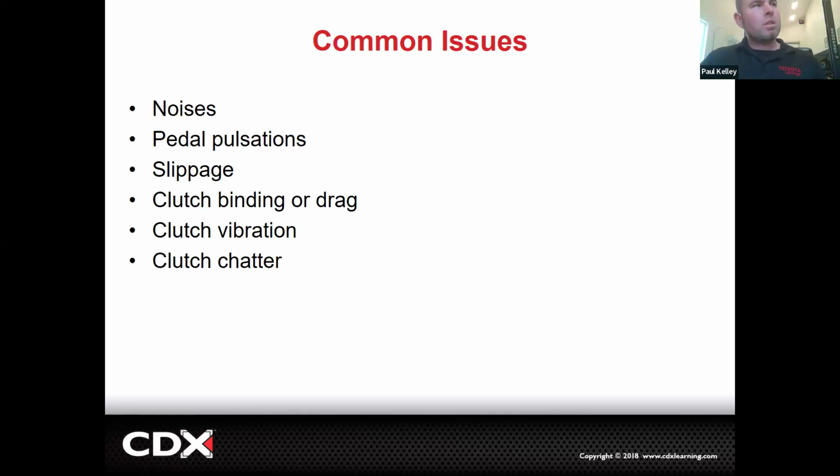Those are very similar to like a chatter. Okay. Pedal pulsations is how the pedal feels. A chatter is like the whole vehicle. They tend to go hand in hand. So a pedal pulsation actually would really only be run out on the flywheel, whereas a chatter is the one that could more be run out, but it could also be the oil because that's going to give you the slip stick, right? But they typically go together. Cool.